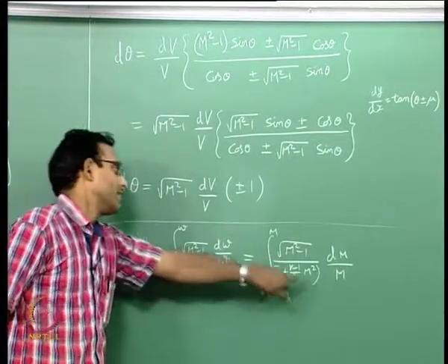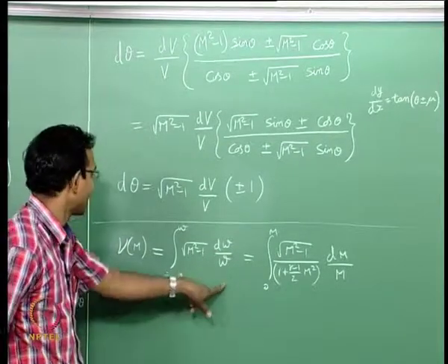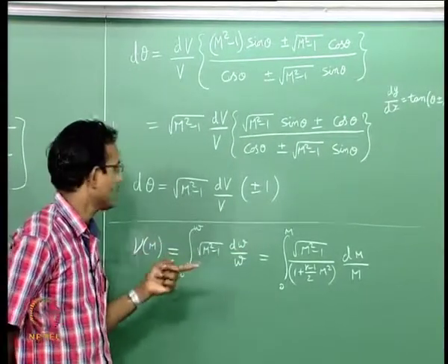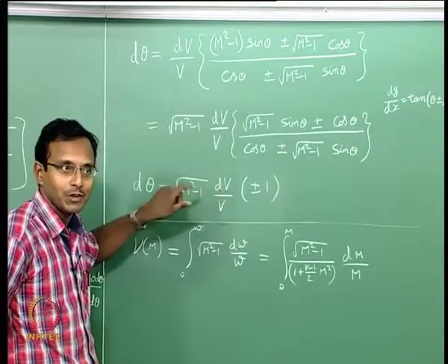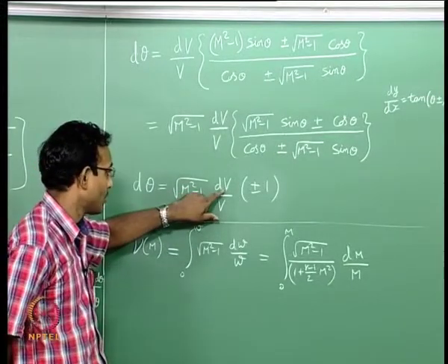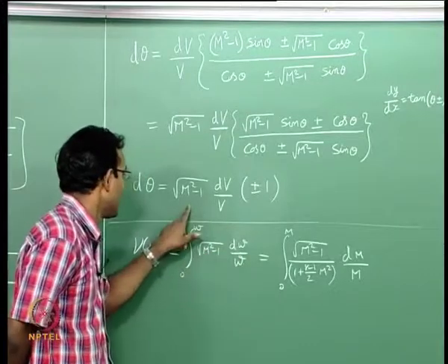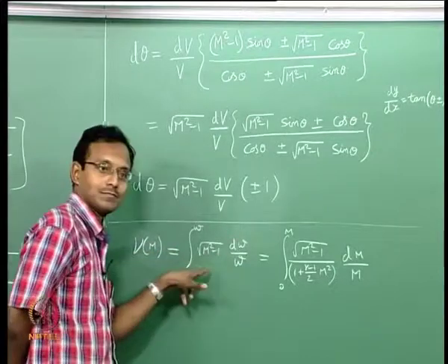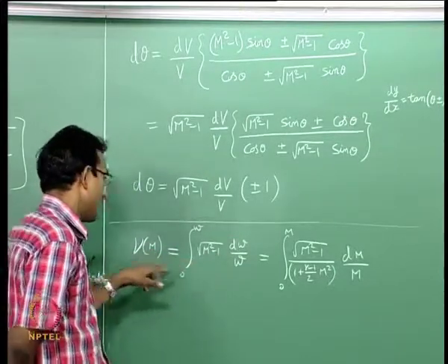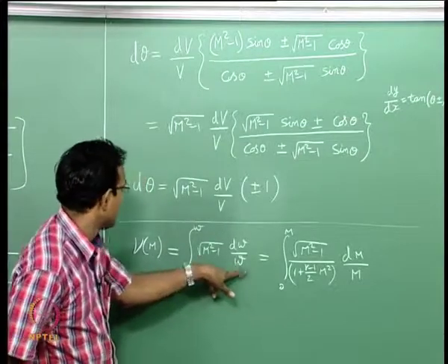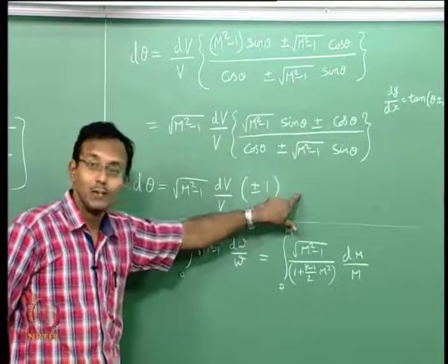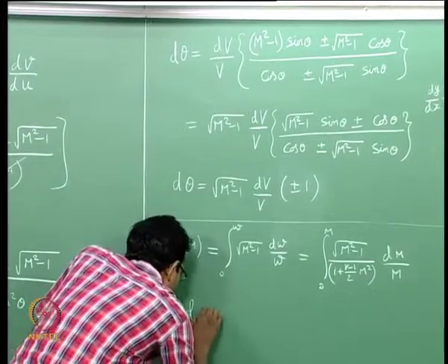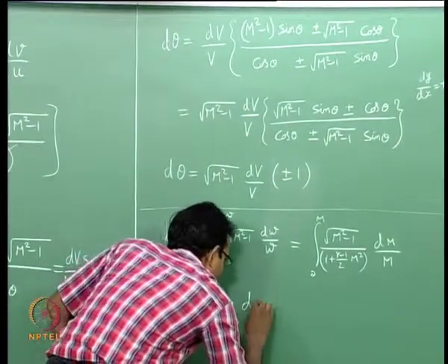Okay. But I want to use this expression now, because this is exactly the same expression sitting here, where we said w is our local velocity vector magnitude. This is also the same thing, capital V is our square root of u square plus v square. So, that is also local velocity vector magnitude. So, this is the expression that is sitting here, which means derivative of this nu will be without this integral, this whole thing, right. So, I am getting to a form where this expression, which is exactly same as this expression, is equal to d nu. Okay. So, now my differential equation comes down to extremely simple differential equation, d theta equal to plus minus d nu.